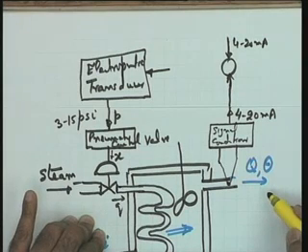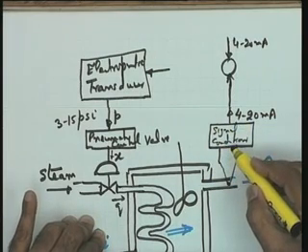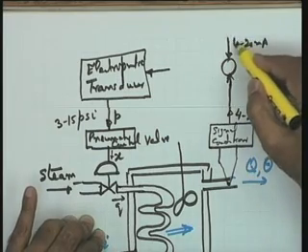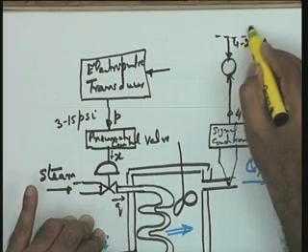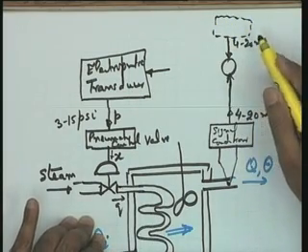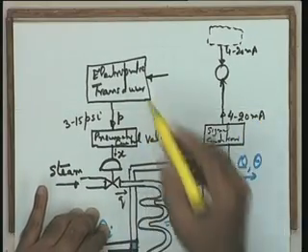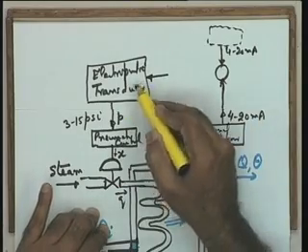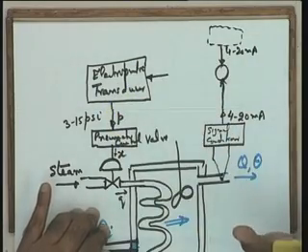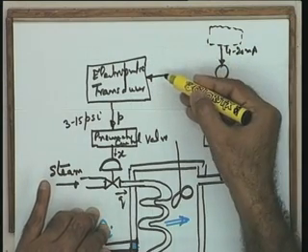Since the signal conditioner constant will be known to me, the 4 to 20 accordingly will be generated depending on the signal, and the generating device over here will be such that the current requirements are met properly. Yes, you are very right, the signal at this particular point after amplification has to be of this range. So, this total system will be designed to meet that requirement. The design of the signal conditioner will be guided by other devices as well, otherwise it may exceed this value.